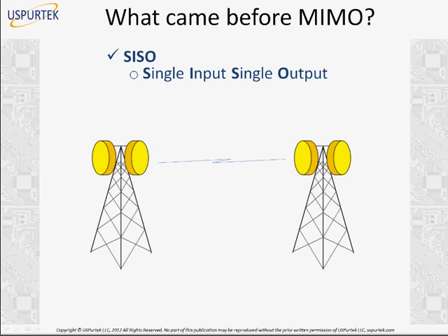From the transmitter to the receiver. Now, there's a question: input means transmit and output means receive? Well, you could say that, but actually, if you take the RF channel as the reference, it is about what we are putting into the RF channel and what we are taking out of it. The RF channel, or the wireless channel, is free space, actually, right? So from the transmitter side, we are inputting our data into the channel, and from the receiver side, we are taking the signal out of the RF channel. So it's very important to clarify this. The reference is not the device, but the RF channel: what we are putting into the channel and what we are taking out. On the transmitter side, we are inputting the signal, so that is the input port, and the output port is where we are taking the signal out of the channel. I hope I've clarified this.